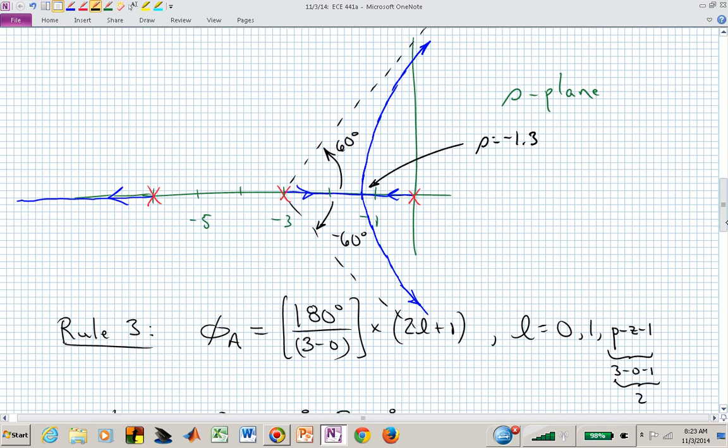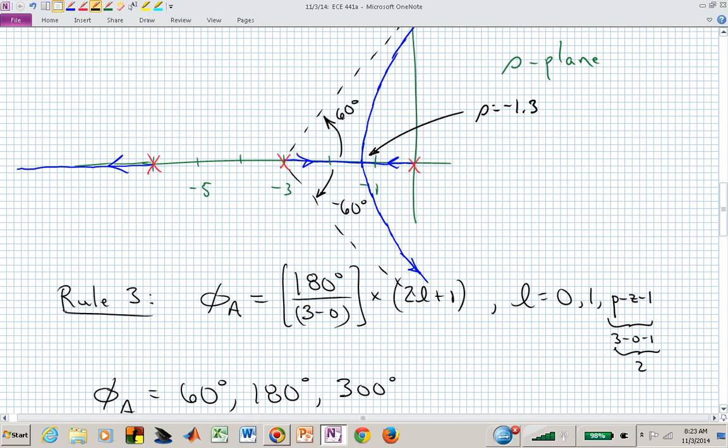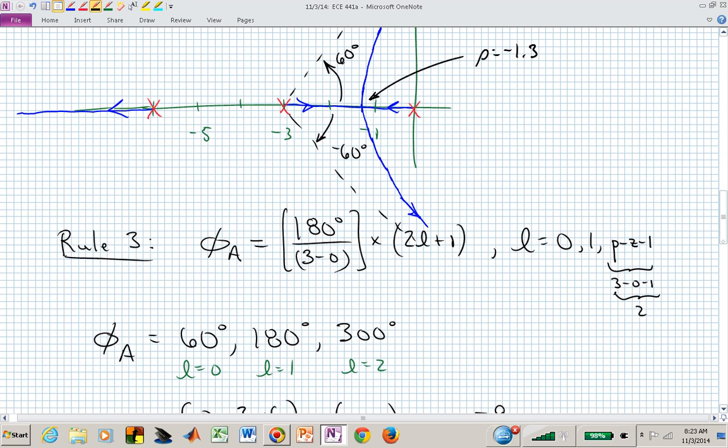Somebody might say, well, I want you to design your closed loop system such that you have two poles at minus 1.3 and the other one to the left of minus 5. How do you tell them what the gain is to get you to that point? Do we understand that these three poles, as we adjust the gain k, are moving along these root locus branches? One is zipping off from minus 6 all the way to minus infinity. Hopefully we won't push it all the way to minus infinity. We might break something. But these two are going towards each other.